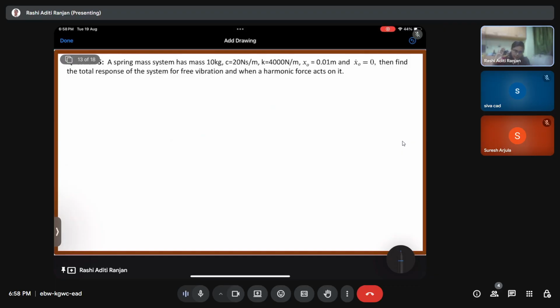I know the equation form. I have the value of mass, I have the value of stiffness, and I know that at t equals 0 what is the displacement, and at t equals 10 seconds after applying the impact what is the displacement of my system. So I can just put it in that equation along with the impact force and I can find out the value of eta, from which I can estimate what is going to be the damping value of the particular system. But then again, this is applicable only for the linear range of the system.